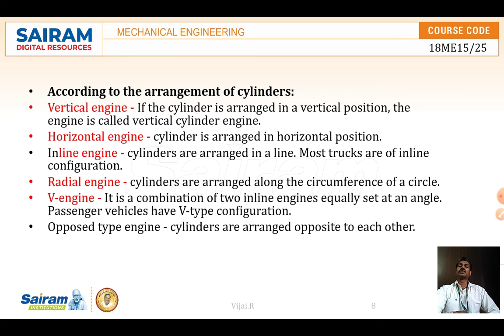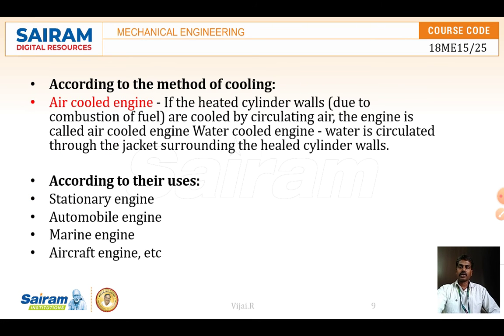Heat engine is the one which produces rotary motion or mechanical motion with the help of heat. The classification we have also seen here. Then cooling also. According to cooling, normally in a two-wheeler when we are riding, fins will be there. You might have seen those fins. They are air cooled engines. Cars, trucks, and lorries all use water cooled engines. The engine is circulated with water, so the water gets the heat, because the engine is producing more heat when the fuel is burning inside.